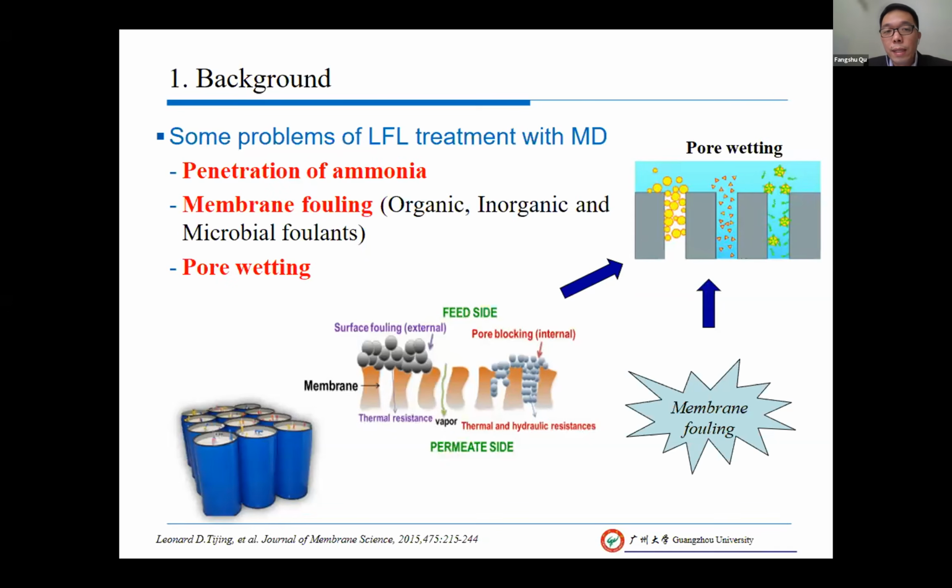But if we use the MD in the landfill leachate treatment, we still meet some problems. The first is the penetration of the ammonia, and the second is the fouling, because there's a lot of foulings like organic, inorganic, and microbial foulings in the landfill leachate. So the fouling issues should be considered. The final one, finally, is the pore wetting.